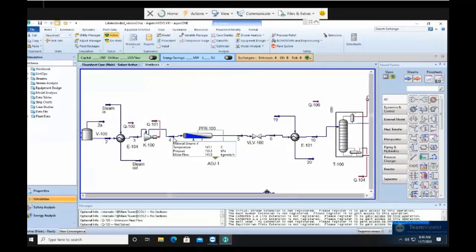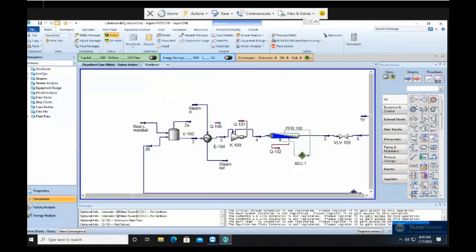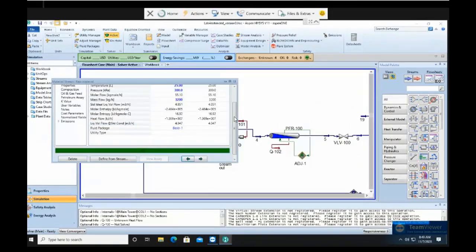After that, you use the adjust button. So the adjust button would be here lah. Okay, the raw material here, because I dah kira-kira that is 3,200 because my recycle stream is 4,800. So initially this one has to be dalam soalan ni kata 8,000 kilogram per hour.